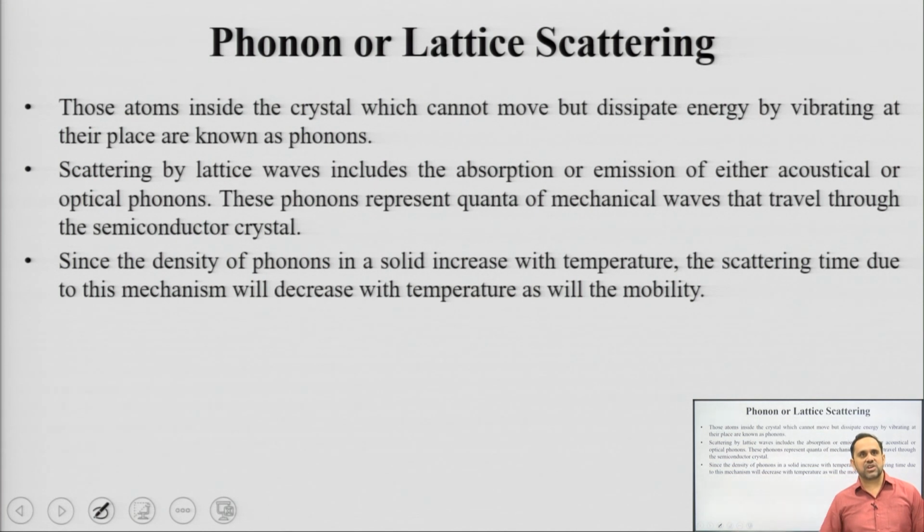When this wave scatters your charge carriers, it can include both absorption or emission of either acoustical or optical phonons. Okay. Acoustical basically means via heat, and optical phonons means when this energy gets dissipated via light. But the basic mechanism is that your phonons are causing an effect on the mobility. These phonons represent nothing but quanta of mechanical waves that travel throughout the semiconductor crystal. The density of phonons in a solid increases with temperature. So, the scattering time due to this mechanism will decrease with temperature, as will the mobility.